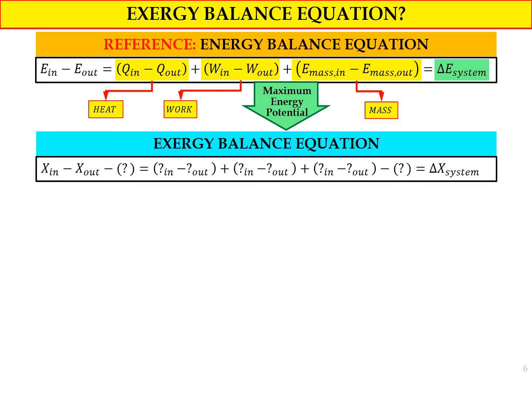So we have a similar pattern for the exergy balance equation compared to the energy balance equation. So for the exergy balance equation we also have X in minus X out plus additional terms that we will learn later on, equal to, if you expand, exergy transfer by heat, exergy transfer by work, and also exergy transfer by mass. And we have an additional term, exergy destroyed due to losses. And the last one we have is the exergy change for different kinds of system.